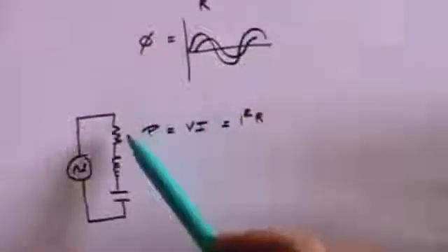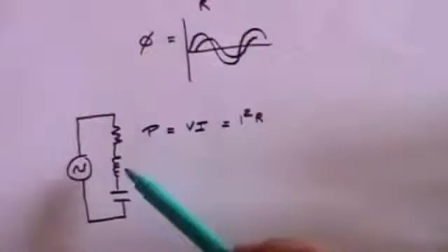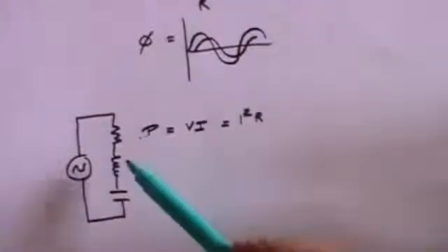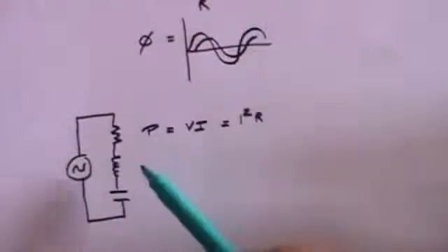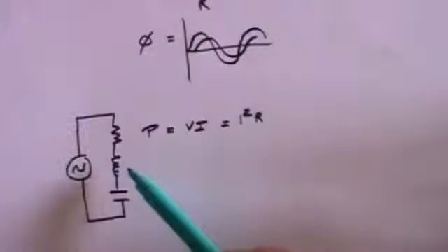We've dealt with this in previous videos on electricity. So there is a power loss in a resistance. But there is no power loss in a perfect inductor or a perfect capacitor. I say perfect because, of course, in practice, there will be some element of resistance in both. But in theory, at any rate, and in terms of exams, you usually think in terms of the theory, there is no resistance associated with these, only a reactance. Consequently, with these two devices, there is no power loss.